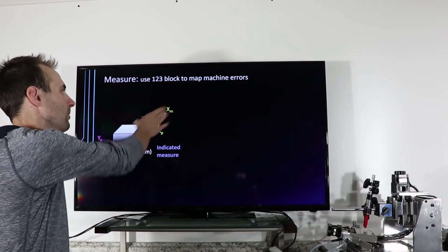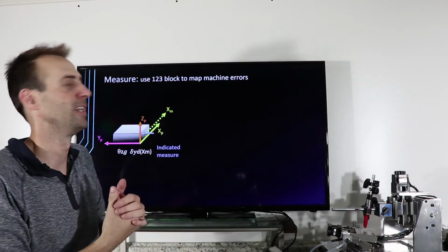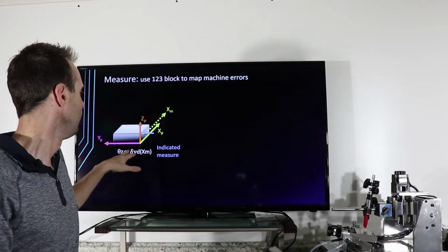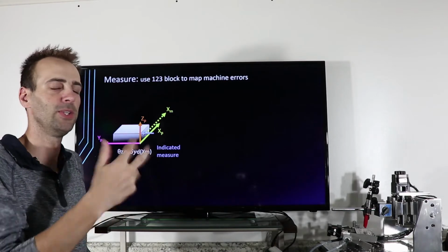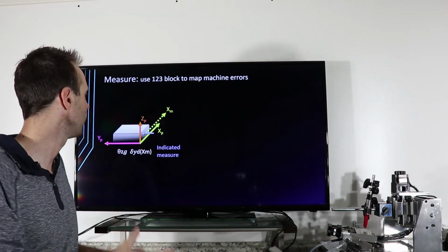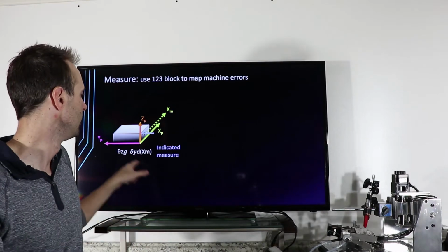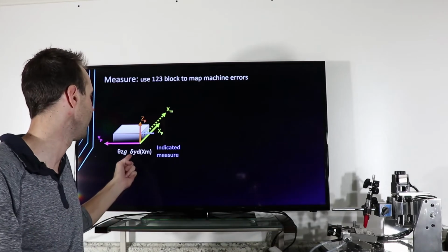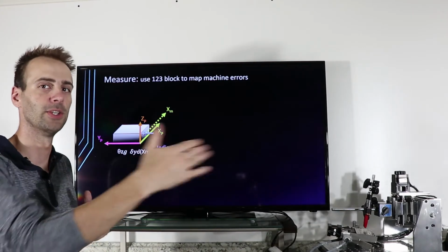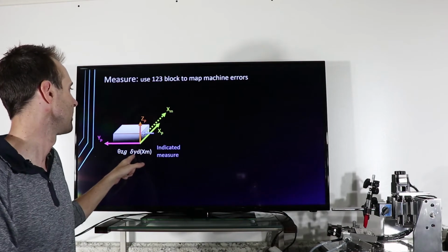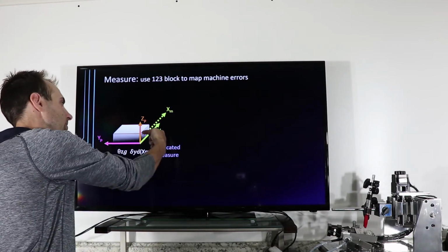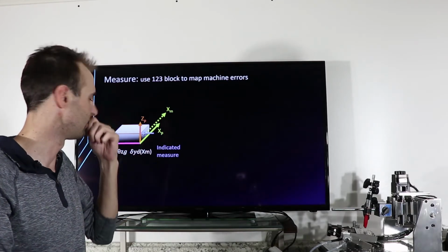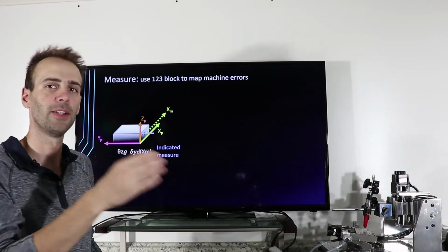So again, I'm going to move the x-axis, so this corresponds to how aligned my x-axis is to wherever I bolted this block, okay? But remember I said that you can't individually isolate each error, so what you could also do, or you could choose to ignore it, is that information also means that you now have a map for the dynamic error as you're moving this along with respect to the y direction, if I'm measuring perpendicular to the y-axis. Okay, so that's why it's really important to, when you're tramming a vise, the scale doesn't matter.